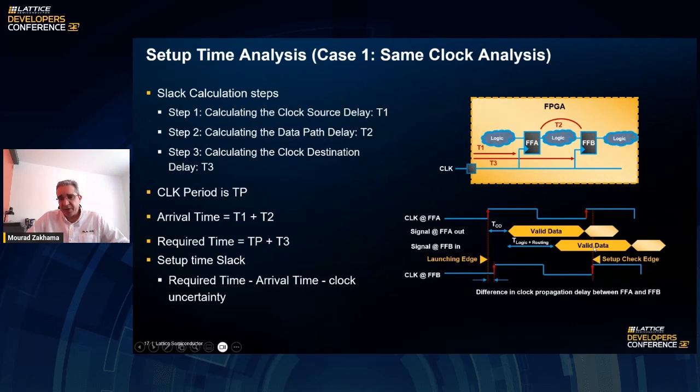So that's where the setup time analysis is done, and as you can see, there's a small difference between the clocks. That's T3 basically, and the addition of these two is T2, plus the clock delay. T1 is the delay it takes the clock to get to flip-flop A. So this is exactly the same process that will be used for every single design, for every single flip-flop.